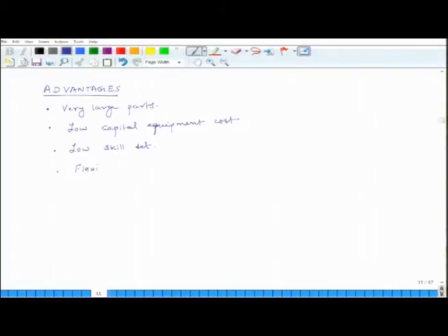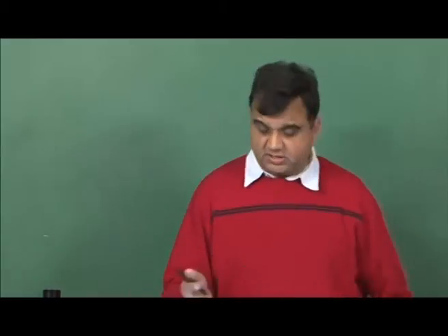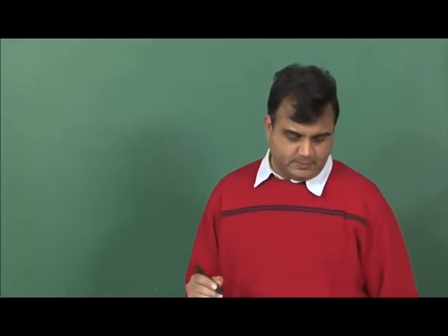It is a flexible method in case of design changes. Because if the design of your part changes, you can very quickly change the tool, which is the molding thing, and you can again do it. In some other methods, change of the tool becomes very expensive, but here it is not the same thing.